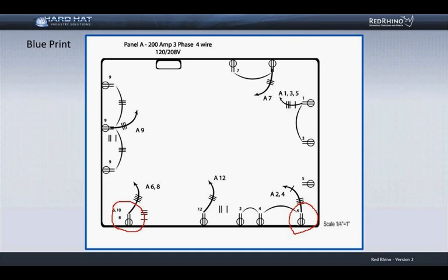When all the half-inch EMT conduits are taken off, I start on 3/4 inch conduits. You get my point here? You take off each conduit size with different numbers of conductors, but you take off all like-for-like conduits with the same size and type wires all at one time. When using Red Rhino Wizard or Conduit Wizard, you can input thousands of feet of conduit simultaneously in just a few seconds.